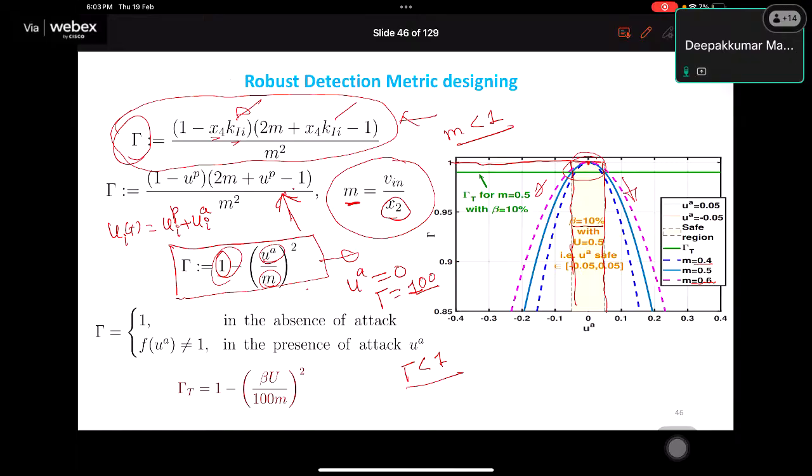So if you know it a priori, then you can always design in such a way that it takes care of all these line resistances. In the design part, you can handle the line resistances. So you can still operate the system without the need of communication. But if you are not sure, like if something is dynamically changing, in that case, neighboring communication is the best solution.